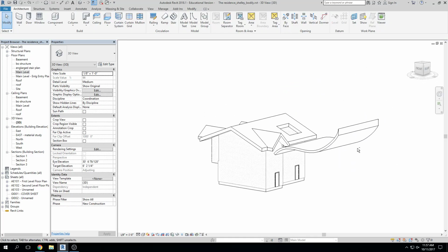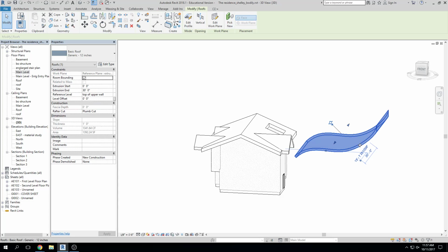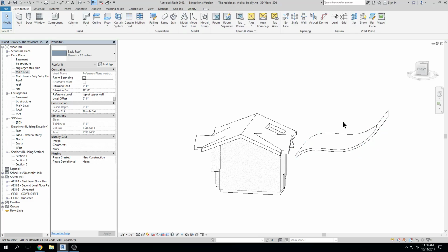Right? And it's a roof. It's an actual roof, right? Which is problematic because you can't really create a ceiling that's shaped like that. Not that you can't, but in Revit, the ceiling tool doesn't have this functionality, right? So you'll have to fake the ceiling in, but then none of the lights will attach to it, right? There's a lot of inherent problems. Not that I'm against something designed like that, but we think in terms of how do you produce that? How do you draw that? How do you make it a reality?